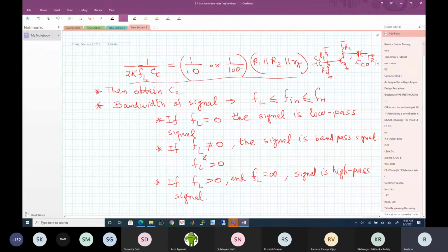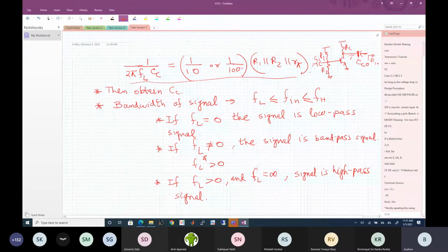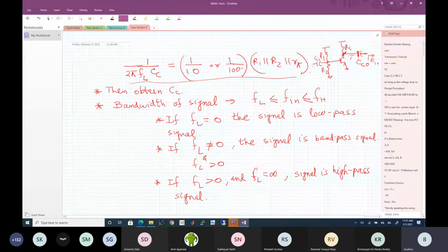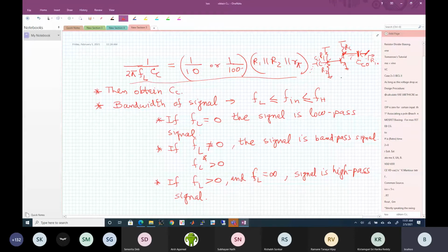So these capacitors do a DC level shifting of the signals. You can see that the signal is swinging around zero, then swinging around a DC voltage, then again swinging around a DC voltage, and now swinging around zero. So they are doing capacitive level shifting. Okay, so this is how you design and cascade amplifiers. If you use a capacitor, unless you can match the next stage DC voltage to this. If the next stage DC voltage is equal to this DC voltage, fine. You don't need to do this. You can directly connect it.